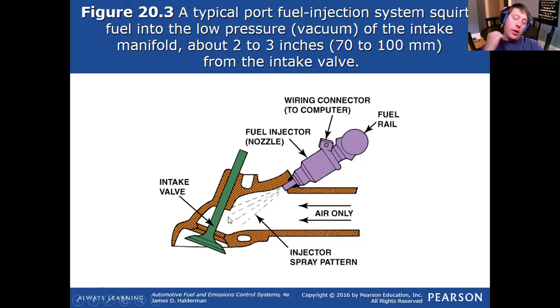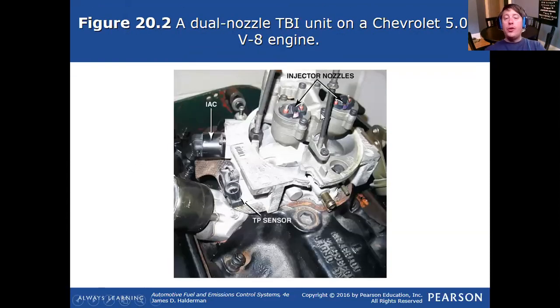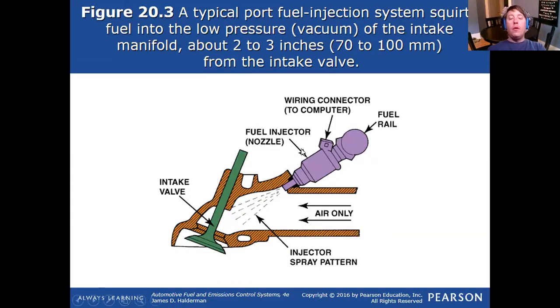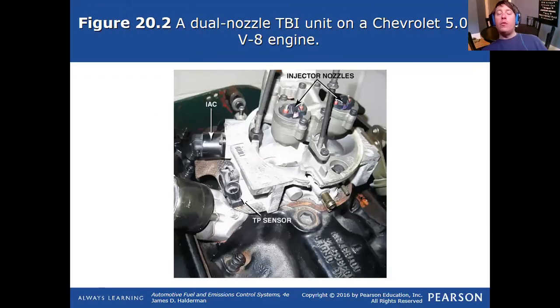I brought up previously, in the last diagram, the location of the injector versus the throttle plate. In this image, we have an injector that is experiencing manifold vacuum pull. In this image, those injectors are not experiencing manifold vacuum pull. This is just a theory point that I want to discuss. It's part of the computer programming and considerations made by manufacturers, and something you need to consider when diagnosing some weird complex issue.